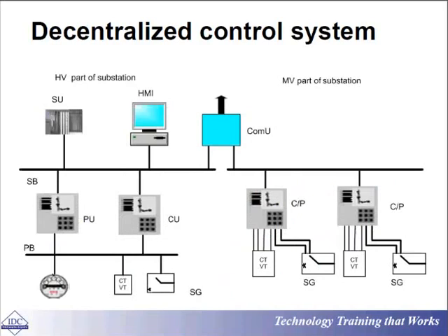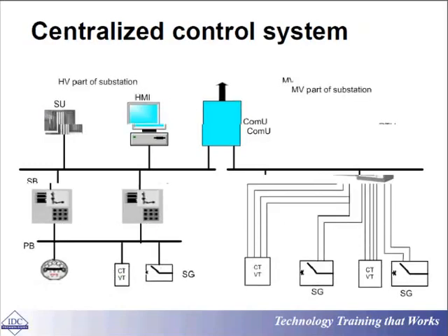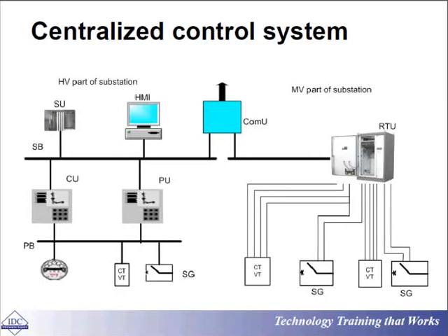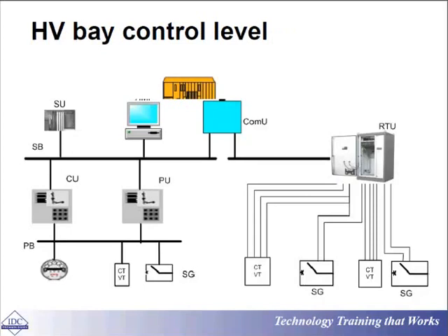As you can see in here, you have got your protection relays, you have got your control gears, you have got many different things in here, right? The HMI, the comms, and something like that. But it is not like everything is based on one thing. These guys are all injecting, receiving, transmitting to the same bus or different buses. So it is decentralized, but you can make it like this, centralized. You can, for example, put your focus on a number of RTUs or just one RTU in here. If you lose that RTU, that could be very, very bad news.